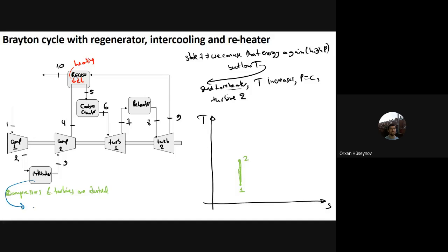delta S, the change of entropy, is equal to the Q in minus out plus the generation. Okay. And for this relationship, if you remember, out was for entropy Q out by temperature, and you have also mass, so mass times this entropy. Similarly, here you have Q in by temperature, and you have this mass times entropy.